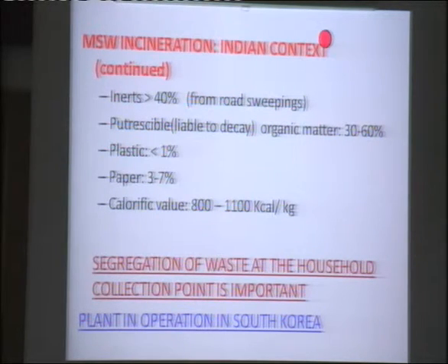Here, waste to energy technology in India, as I was talking about, is generally biomethanation, landfill with gas recovery, and composting. These are the practices in India. But for MSW, there is no incineration plant in India, because whatever waste is obtained is not self-burning. It contains a lot of sweepings and all such things that are put into the dustbin. So it contains incombustibles, and that cannot be burned.